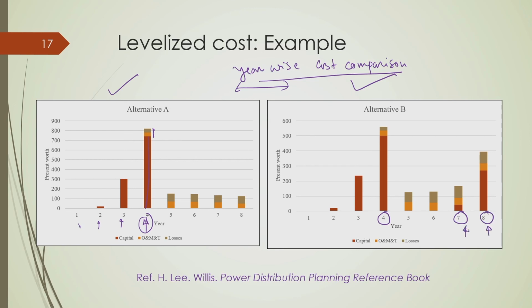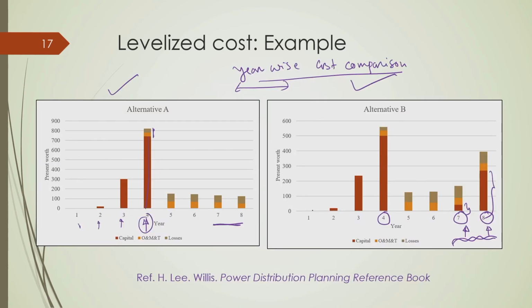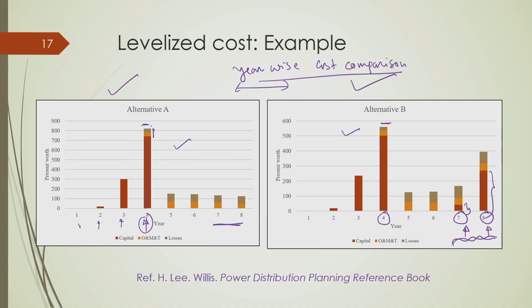Okay. And why is it high compared to these two? Because here we take the decision to install another transformer, which accounts for a considerable amount of capital investment cost. Okay. All right. Whereas, here the present worth cost is around 500, here it is much higher than that. Okay. So, these two are different scales that one needs to notice, although they look like the same thing, but this is up to 550, here it is around 800.